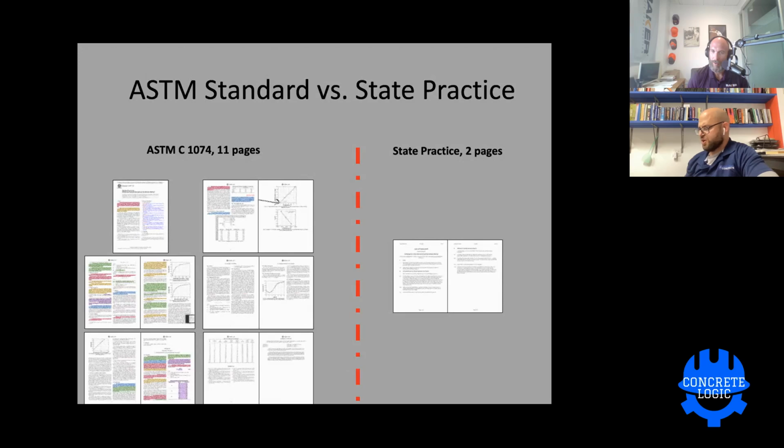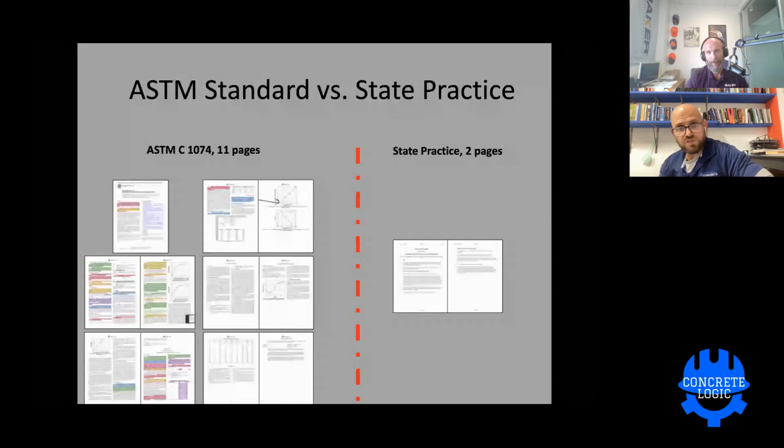I think that is a general statement. I don't know why they needed to include that. I think you're adding something that is unnecessary. Somebody might have brought it up and it was a point of contention that they're not going to let go of the negative unless you put this in there. But that's when we don't know what later age strengths are going to be based on early temperatures. A 90-day strength is not going to be dependent on a 24-hour or 7-day temperature change.